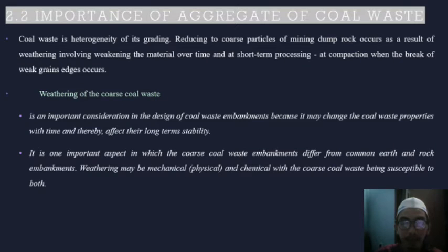The second thing for the literature review is the importance of aggregate of coal waste. Coal waste has heterogeneity of its grading. Reduction to coarse particles of mining dump rock occurs as a result of weathering, which weakens the material over time, and at short-term processing, which is at compaction when the breaking of weak grains occurs.